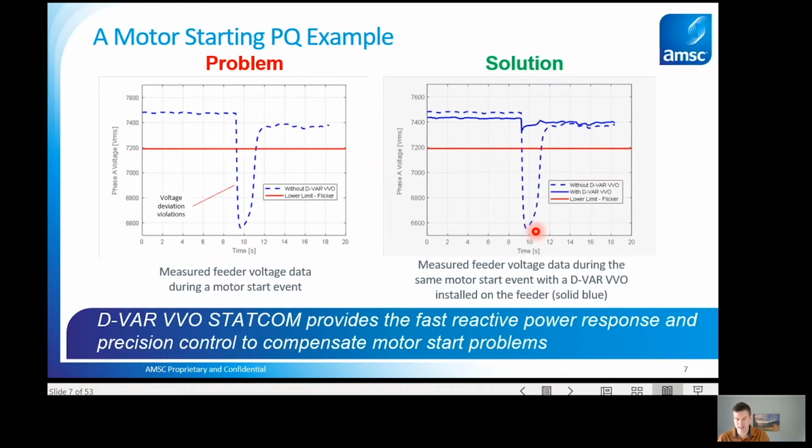And we can see that that power quality problem is just totally addressed. And this is now just by canceling that reactive power near the motor. So really emphasizing that, yes, this is a reactive current problem, not a real power problem. If we address that reactive current, then we can nicely expect to solve that problem.